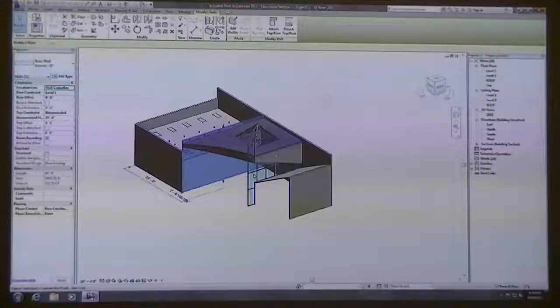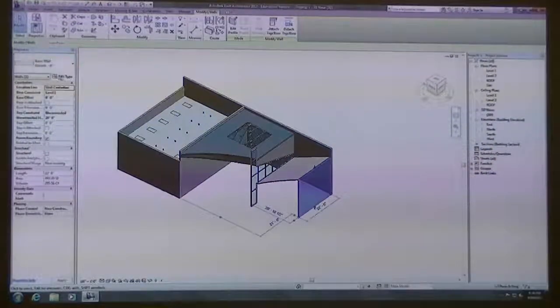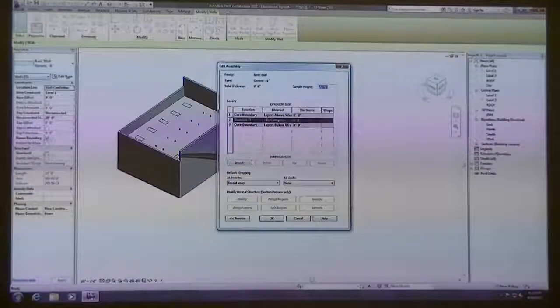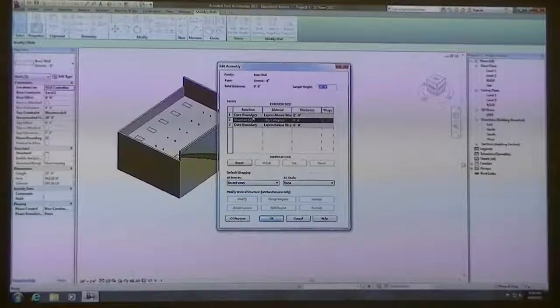Anyway, all right, back to BIM methods. One of the things we've really just dealt with as far as walls are concerned is making the different layers. You can click on the wall, click on edit type, and we talked about editing the structure and adding in different materials such as additional layers of gypboard and that kind of thing.